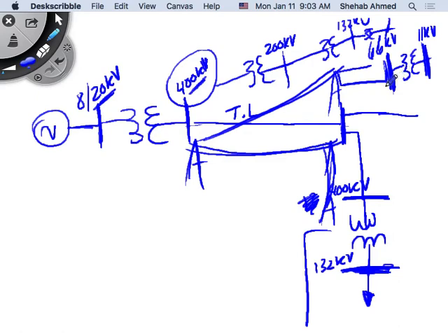So there's a series of transformers, right? And Kahrama manages all of these. And then there are consumers at different voltage levels. The bigger consumer you are, the higher the voltage level you will probably take power at, because it's going to be cheaper for you. Why is it going to be cheaper? Because you're going to invest in building your own power system. Kahrama will sell you power at 132 kilovolts. Ras Laffan City, you take care of yourself, right? Until it gets to what? So this is 11 kilovolts, right? This is the 66/11 that is in that building, right? 66/11. Then what happens?